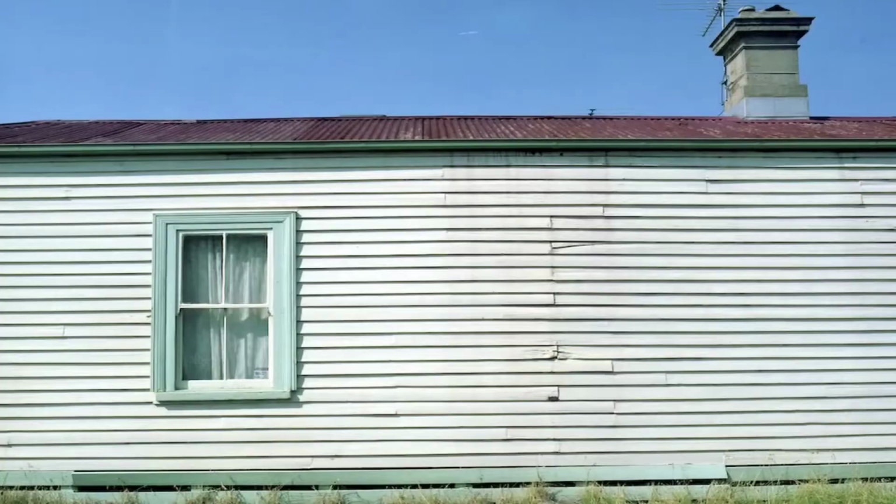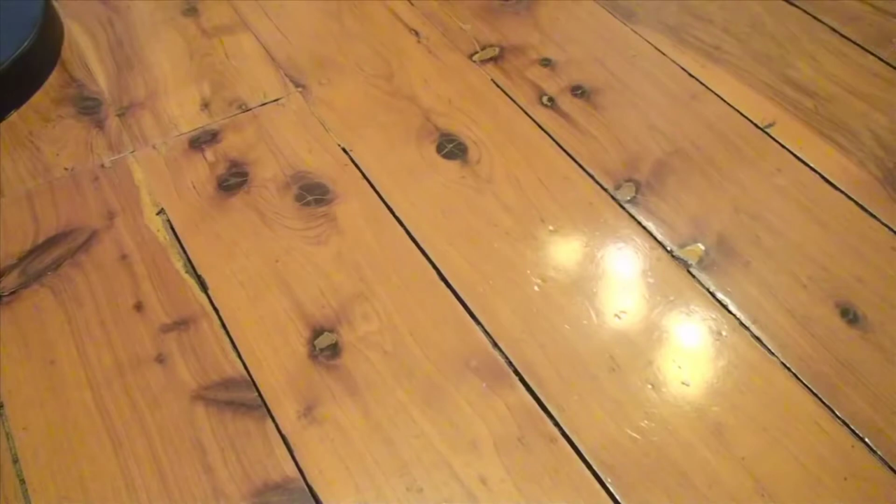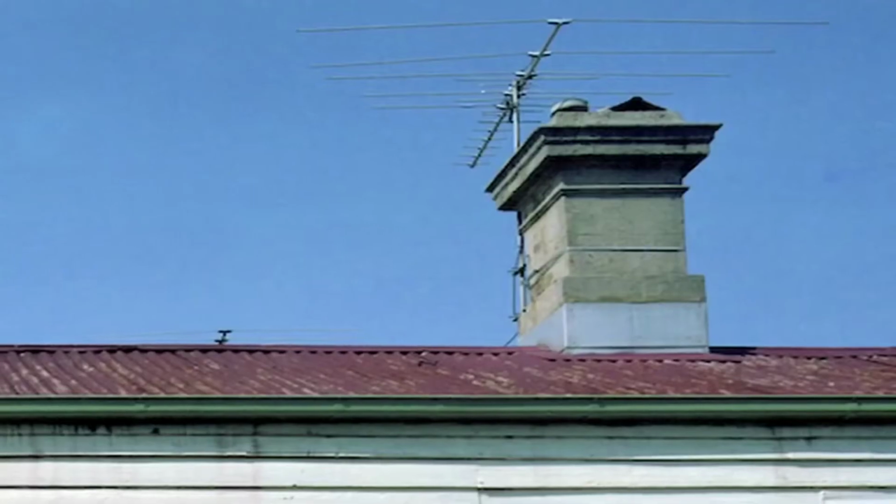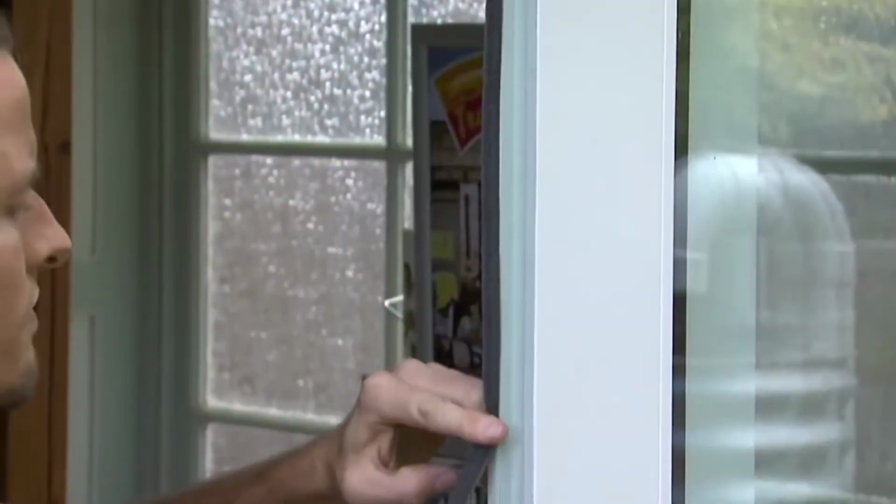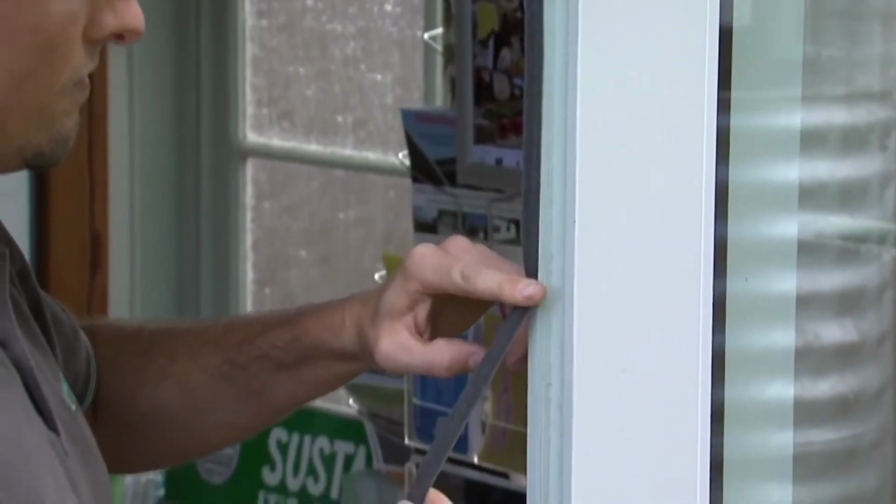A well-insulated building envelope is of little use if it's not well sealed. A leaky house might have 20 air changes per hour. The air inside gets replaced every few minutes. Drafts like this are a problem in cold weather and also in hot weather. Make sure you've got good seals on doors, windows, chimneys, exhaust fans and recessed downlights. There'll still be enough fresh air to keep people healthy.